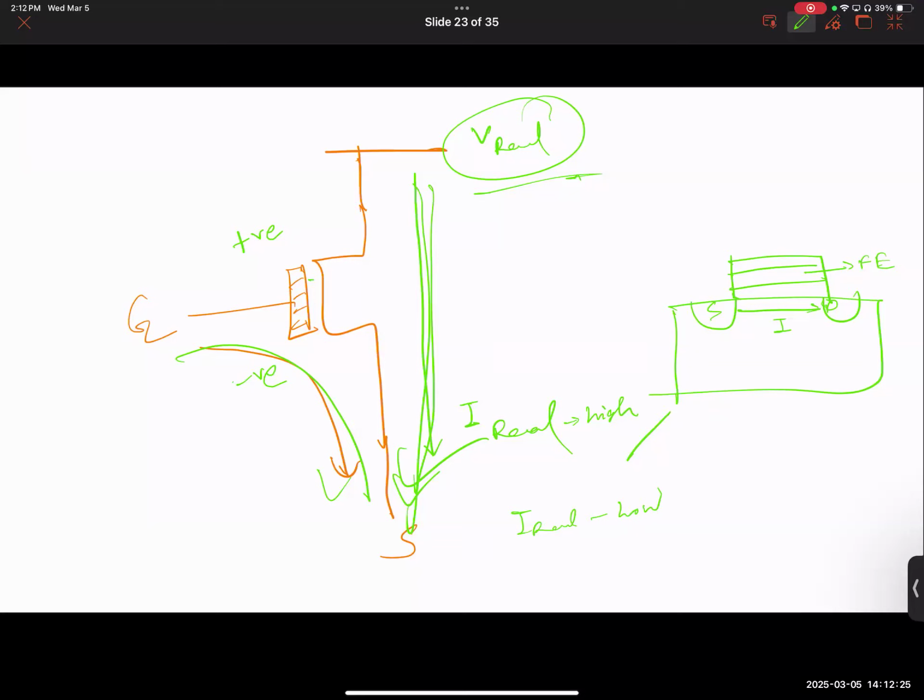STT or SRAM, you mean SRAM? No, SRAM has the same read-write path. Okay, but there are some flavors of SRAM. You're right, actually. Remember, we talked about 8T, 10T, 7T, right? There are other T SRAMs, not 6T, not the standard one. So we had to use additional transistors to achieve a separate read-write path.